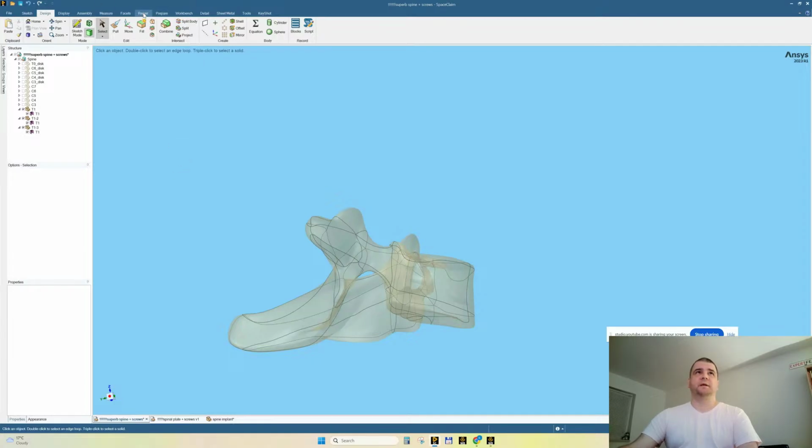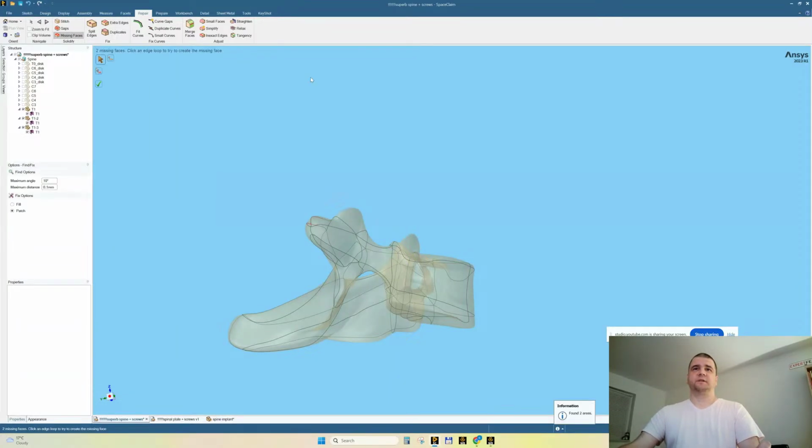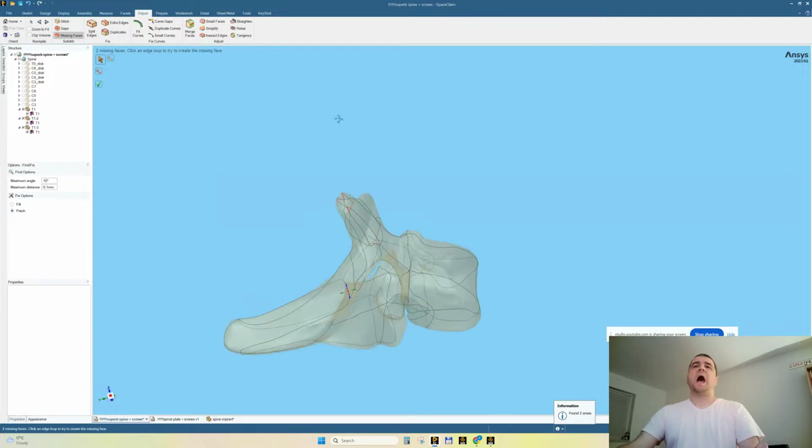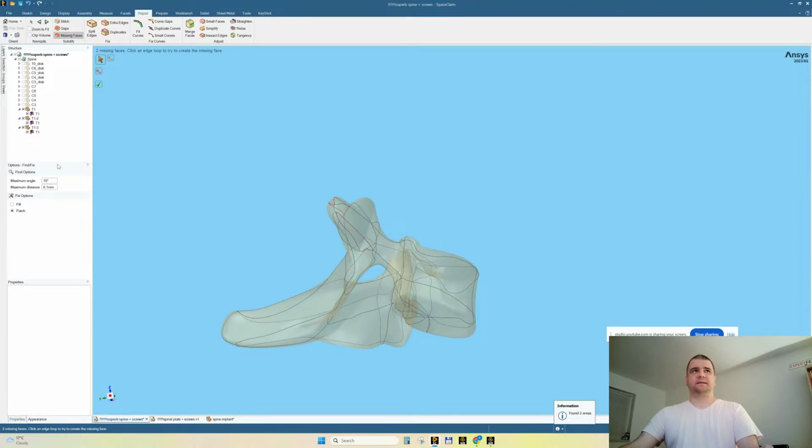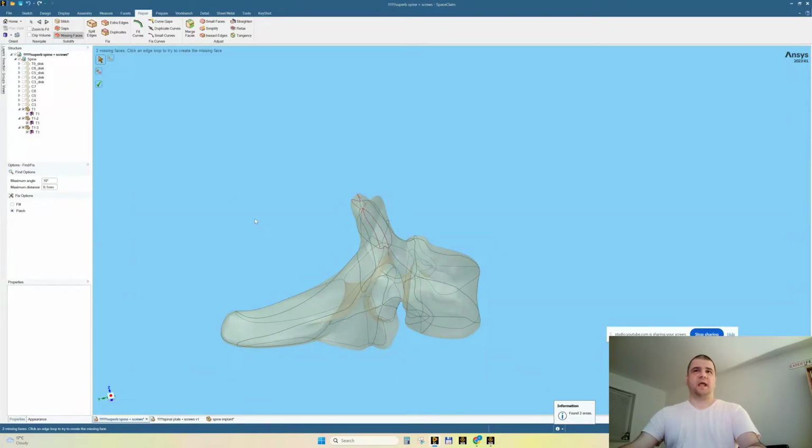So we have the repair tab. Usually I'm going for missing faces, usually. Let's see if it works with this. You know what? These faces exist. Yeah, there are these extra faces. So I will not heal as it is. Instead, because these faces exist separate, I will go for something called maybe stitch. There are no stitch, all right. Maybe gaps, no. So it's done.